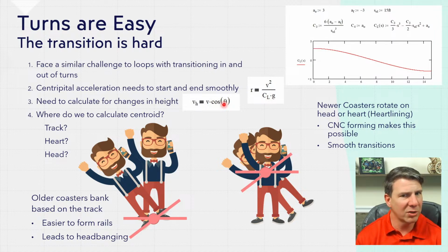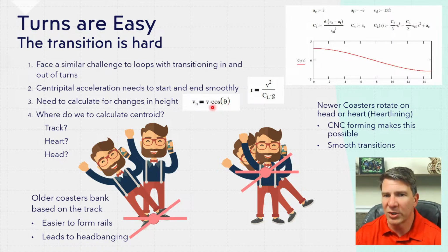However, you don't have a large turn radius to deal with that because a lot of your velocity is in the downward direction and not the horizontal direction. So what we want to do is multiply our velocity times the cosine of our pitch angle. As we're going further to vertical down, our horizontal velocity is going to become closer and closer to 0.